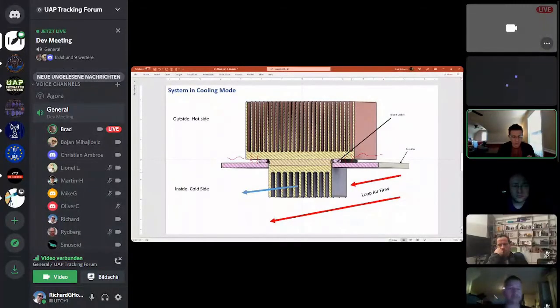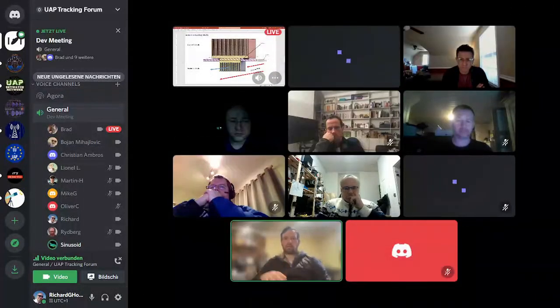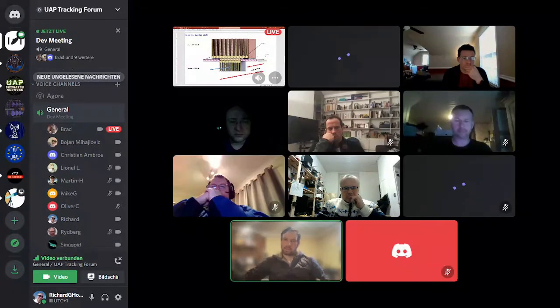If the thermal exchange is a function of the difference in temperature and area, and we're kind of limited on area, we have to get the small heat sink very, very cold. Typically, when I've seen these configurations, there's a fan mounted directly on the cold side, pushing air through it. On the hot side, usually no fan. I'm speaking very generally, but when the unit reverses and operates in heating mode, the cooling fan can turn off because the system's pulling heat from the outside. So I would think you'd need to have a fan directly on that cold side. I think in the configuration that was shown, the fan was somewhere else in the enclosure. I really think that's going to have to be right on the cold side of the heat sink in order to get that ideal delta T.